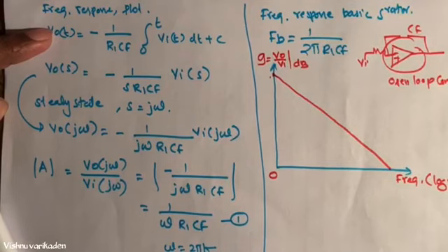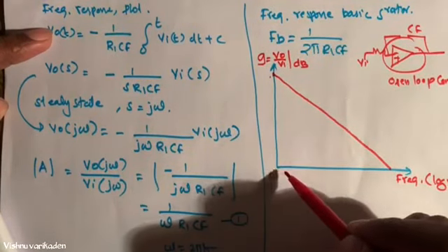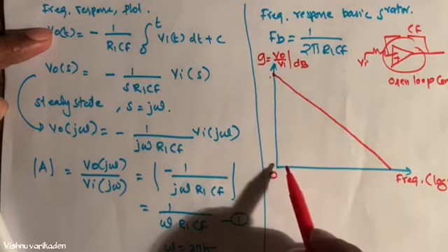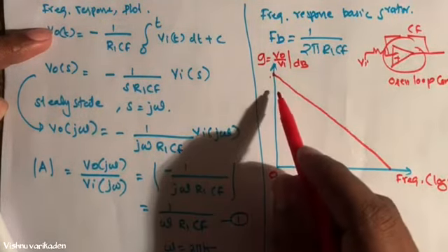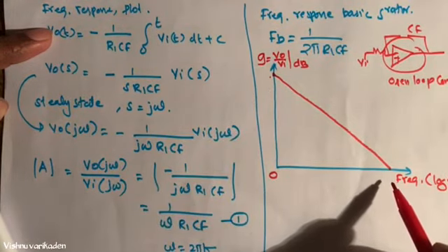This is the ideal op-amp condition. Now we need to think about the practical op-amp condition. We move to it because whenever the frequency is zero, or DC, or below a certain value, the gain goes to infinity. That is one of the problems of the ideal integrator, and we need to overcome it.